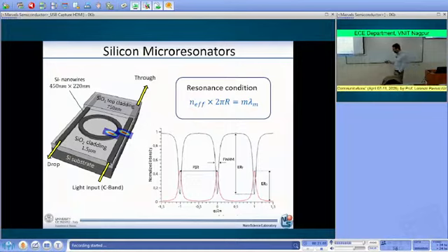Okay, yes. So this is what I was saying before. Some light is still trapped inside the microring resonator. But at the same time, the waveguides are characterized by some losses, and therefore some light is lost. Okay? And so you have the sum of the light that is transmitted in the through, plus the light that is transmitted in the drop, plus the light that is stored in the microring resonator, plus the light that is lost, and these four quantities should sum up to 1.